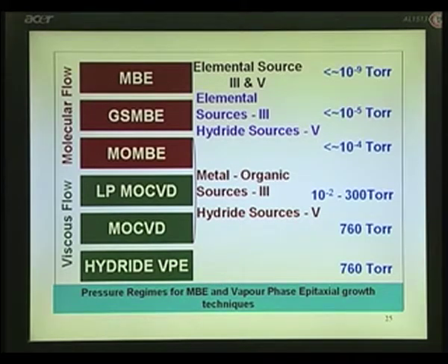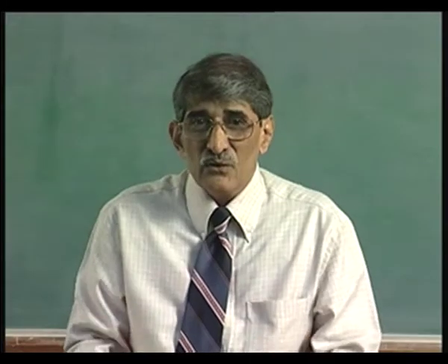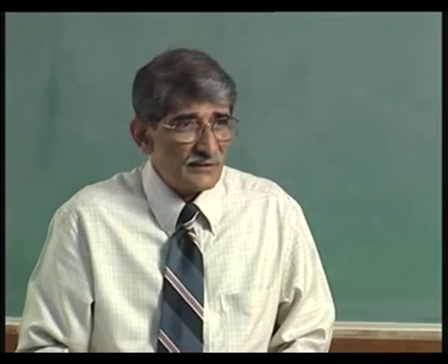So, when you put a wafer like this, you can put one wafer behind the other. If the gas is flowing at atmospheric pressure, and you put the wafer vertically in the furnace, it will deposit on this, it will be blocked. If you go to lower pressure, the mean free path is long, so the gas flowing here can flow like that all through. So, the hindrance effect is not there.